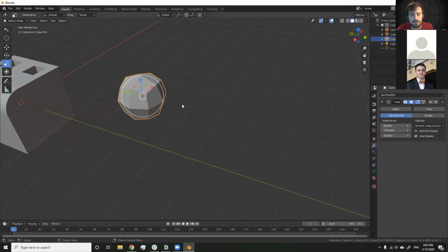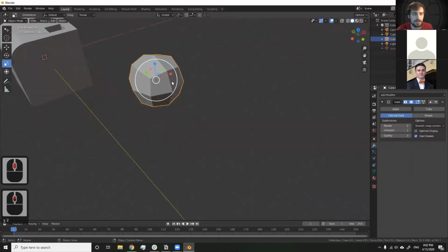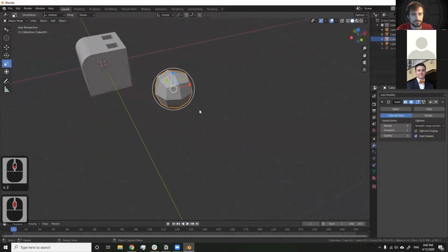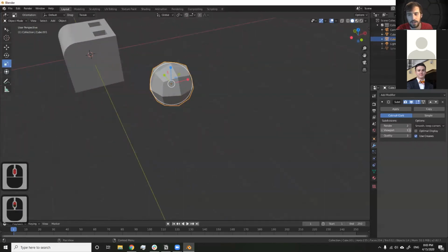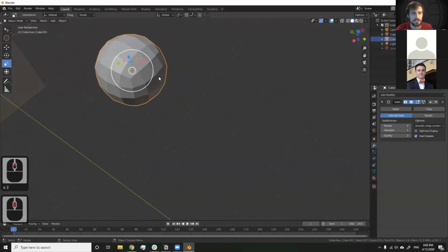This saves computation time in your viewport, so everything stays nice and fast, but you want to keep in mind that it's always slightly more subdivided in your rendering when it goes to actually make your final image. In general, I like to have them matched together so that I don't switch to render and then forget that I had more subdivisions in the model than actually were showing up in the viewport here. So 2 subdivisions gives you this shape.